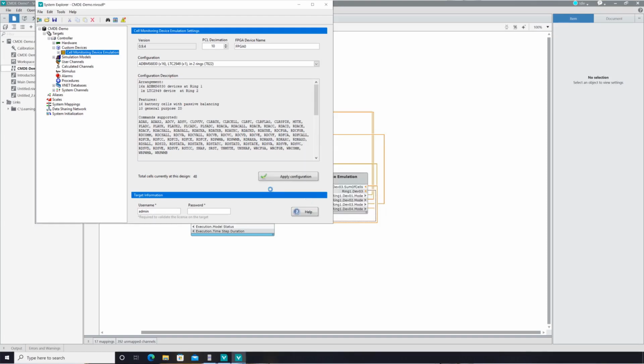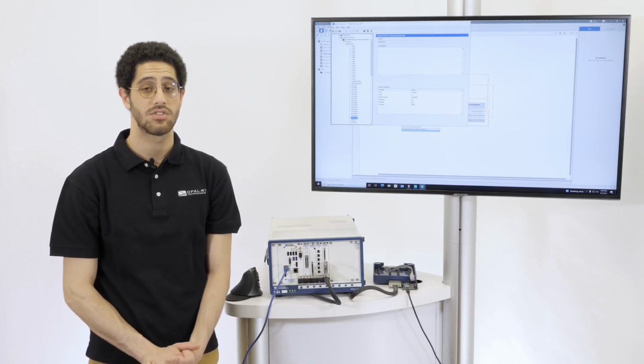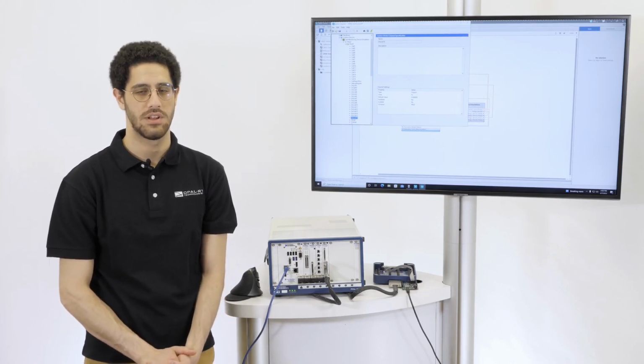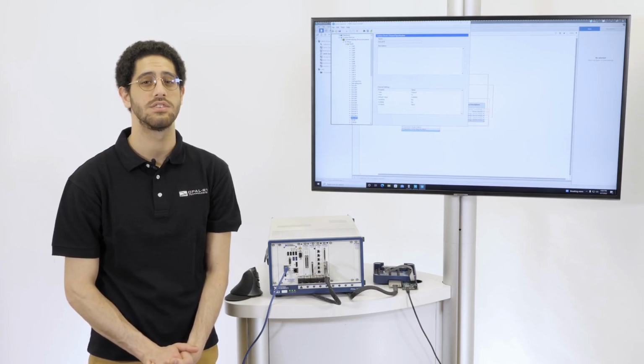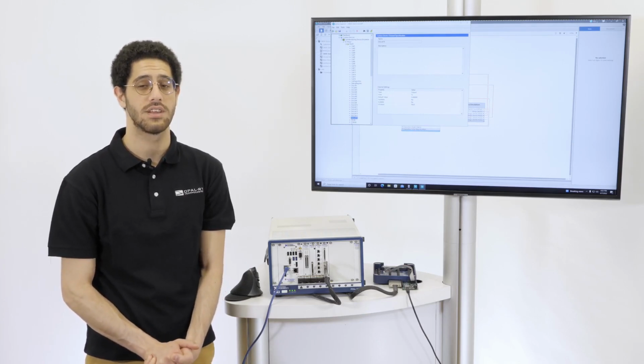For example, over here we have the ADBMS 6830 that supports 16 cells. It also supports a cell open wire function and the discharge function. The discharge is the rate of discharge of each cell. In our tool, we've added the rate of discharge function into the FPGA simulation so that if you select the rate of discharge of 30 minutes, it'll take a real 30 minutes for the cell to discharge.